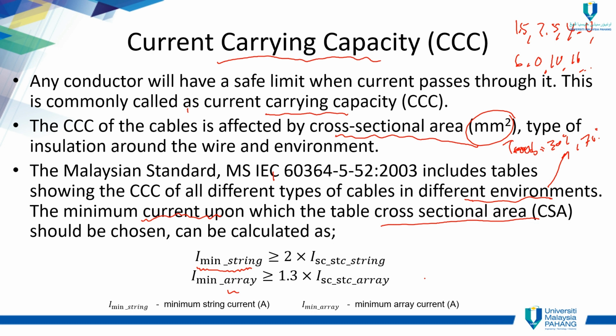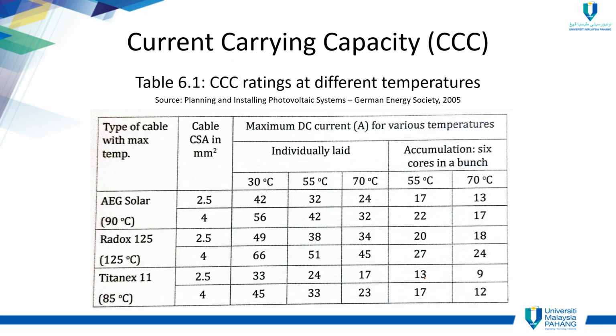Okay, it's all in the cross-section area lah. Maksudnya, depends on the cross-section area. Then we find the cable that is suitable for this kind of application. Kita tengok sini. So this is Table 6.1, the current carrying capacity ratings at different temperatures.